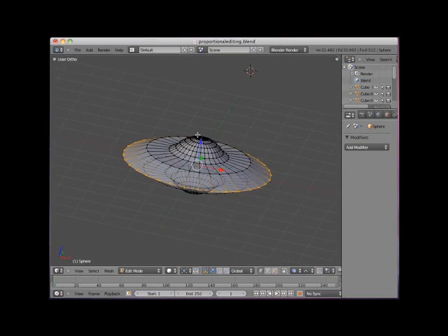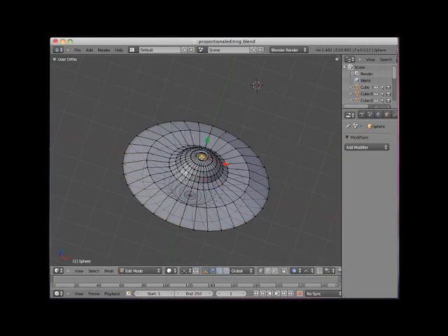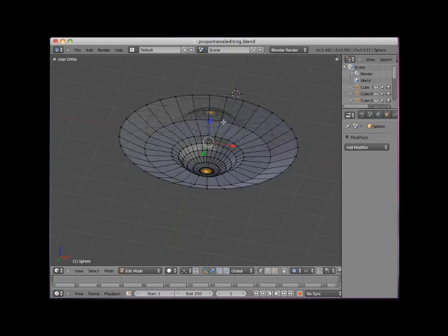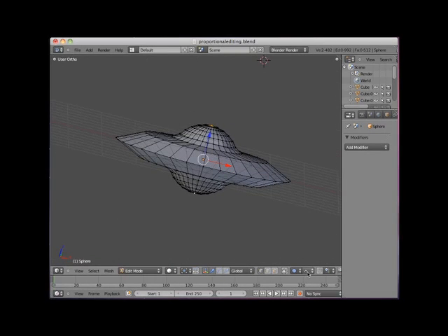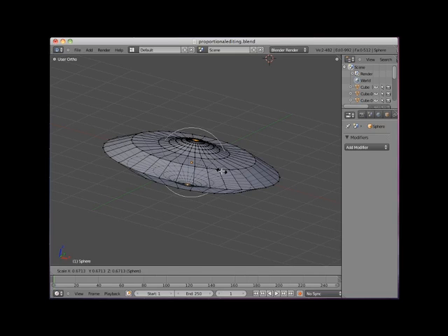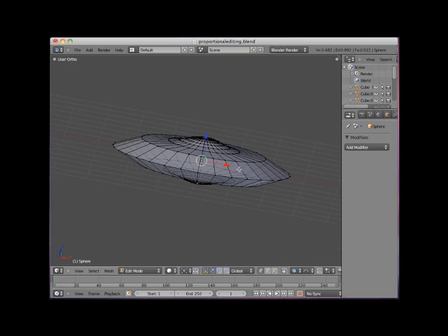I'll then select the top and bottom vertices, change the falloff pattern to sphere, rotate my view a bit, and then press the S key and scale down, adjusting the influence circle to encompass mostly the center part of the sphere. I'll tab out of Edit Mode.